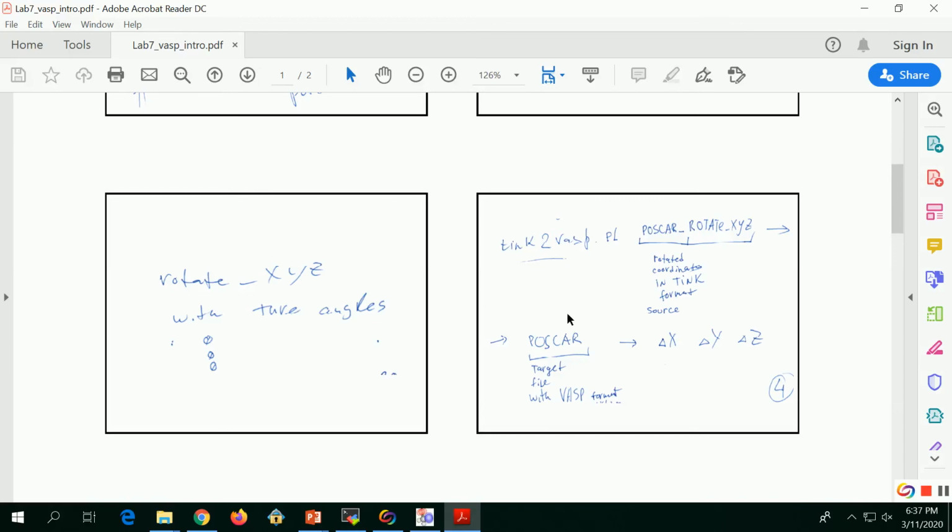This is a little handwritten code, and you may find ways to convert input files into VASP in some specific crystallography software, but this is a shortcut. So we type this script, then the name of the file that was created upon rotation, then the name of the file that we are going to create, POSCAR, and after this there will be 3 numerical parameters.